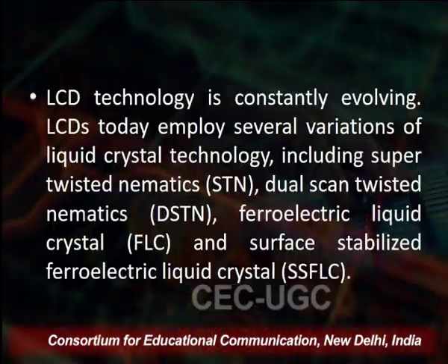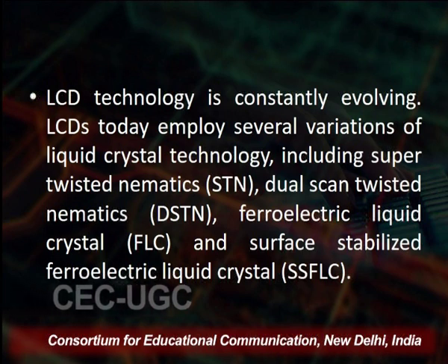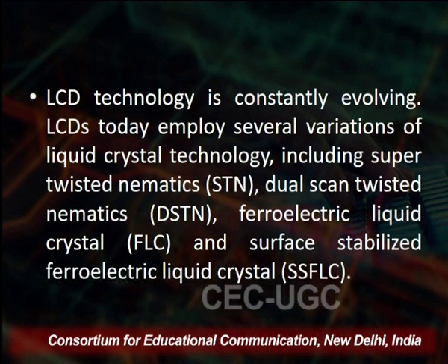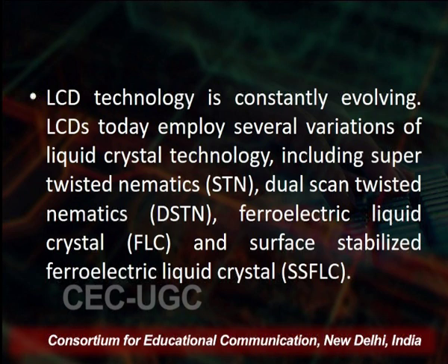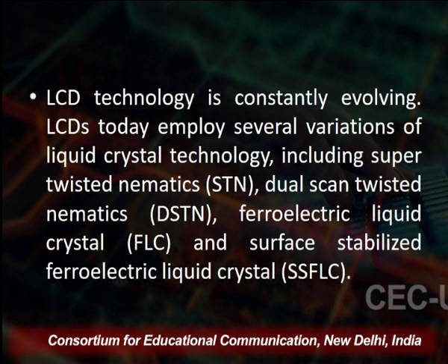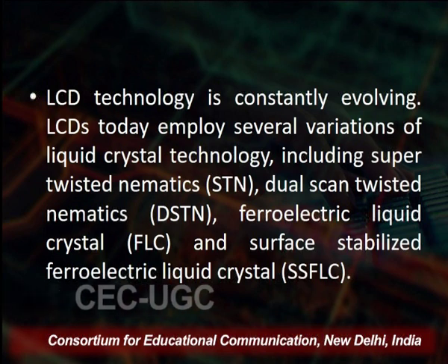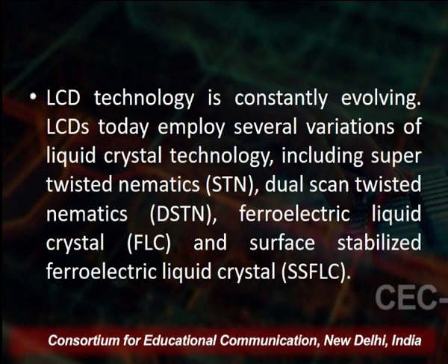LCD technology is constantly evolving. LCDs today employ several variations of liquid crystal technology: super twisted nematics, that is STN; second, dual scan twisted nematics, that is DSTN; ferroelectric liquid crystals, that is FLC; and surface stabilized ferroelectric liquid crystals, that is SSFLC.